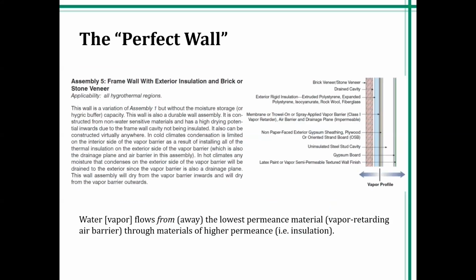And the drying scenario, if we look at where the gyp sheathing is in this wall assembly, it's effectively buried within the most centermost portion of this wall assembly, so the ability of that gyp sheathing, which is moisture sensitive, to release that moisture will not likely happen in hours, days, or weeks. In some scenarios, it can actually take months. And I believe one of my CSI colleagues who works in hydrothermal analyses said he had one project where the gypsum didn't release that bound moisture for 3 or 4 months.